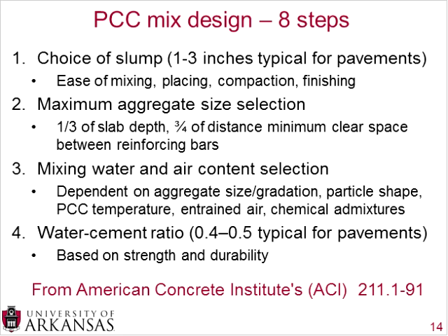The next step, step 2, is to determine the maximum aggregate size. And the maximum aggregate size rules are pretty straightforward. An aggregate cannot be larger than 1/3 of the slab depth. So if you have, for example, a 1-inch aggregate, you need a minimum of a 3-inch slab of PCC.